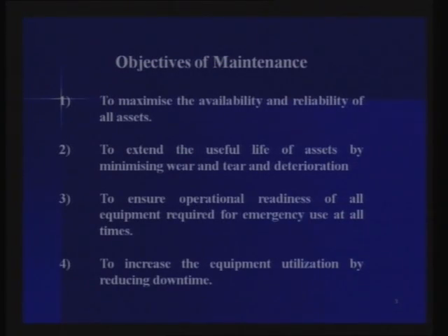Now, what are the objectives of maintenance management? To maximize the availability and reliability of all assets. These two terms, availability and reliability, have been coined from the military establishments. Military equipment should always be available for operations. That we call availability. We try to maximize the time it is available. Reliability is defined in a different way: the probability of how long this equipment or component will work under specified conditions, that we call reliability.